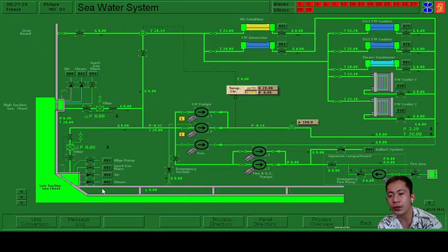So we will use the low suction switches on this valve and trace up the line and open the diesel generator number one freshwater cooler. Since we will start preparing diesel generator number one, then we'll go to overboard. Since the piping is now okay, we can now start our auxiliary pump.